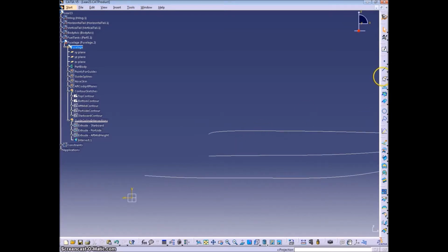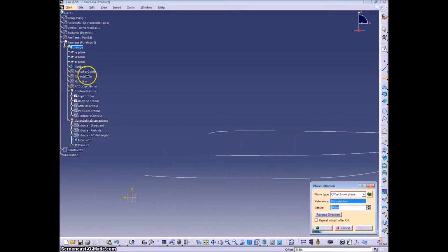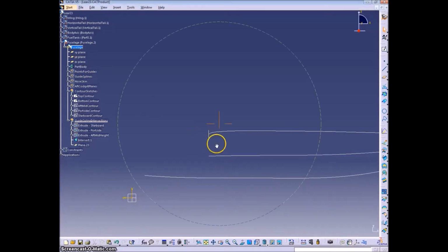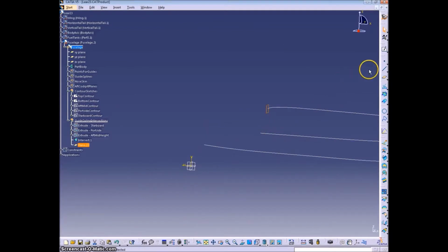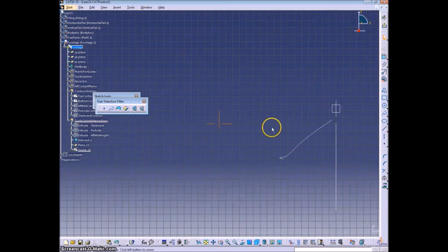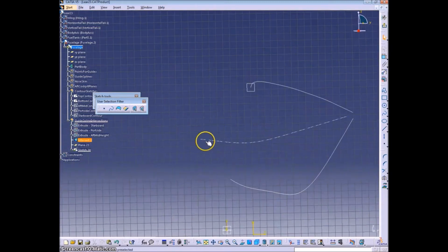But the next step is to create cross sections, which we will make out of ellipses. To do that, we'll put in a plane through those two endpoints, enter the plane in a sketch, and project, or well, we want to intersect them with the plane, intersect 3D elements.